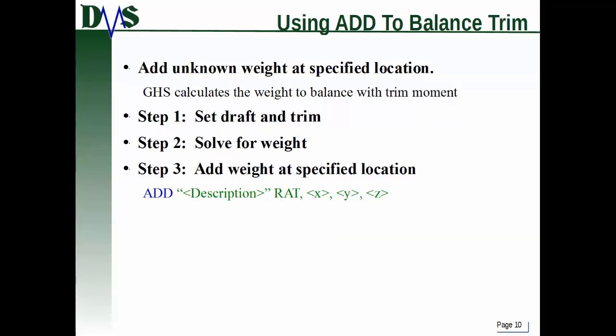And you can also use it to balance out trim. So what you would do at that point is you would set the draft and trim. You're going to solve for weight is the next thing you're going to do. So you'll actually equalize your draft basically. And then you will add another weight to equalize your trim.